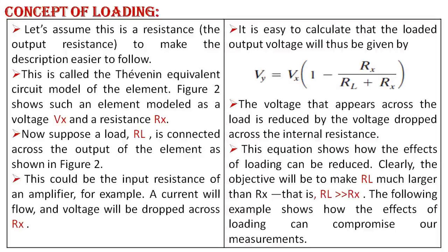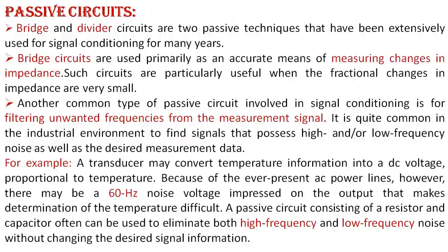This equation shows how the effects of loading can be reduced. Clearly, the objective will be to make RL much larger than Rx. That is, RL is much greater than Rx. The following example shows how the effects of loading can compromise our measurements.